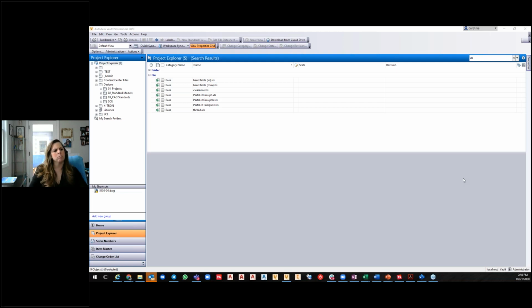Yeah, so if you're working outside of a different working folder, so if people have different working folders defined, that's a little bit different. What I meant was, if you've got your local working folder of C:\Vault working folder, and she's got hers as a C:\Vault working folder, you open drawing number 1, which has a contact on it that has a relay on it. Then Tiffany's working on drawing number 2, which has a contact related to that relay. Those files are now disparate.